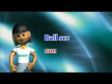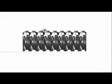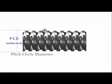Now we will introduce the contact geometry of ball screws. Pitch circle diameter is the diameter of the circle formed by the central diameter of ball screws' upper and lower ball bearings. The lead is the distance traveled by the nut when the screw turns one rotation.